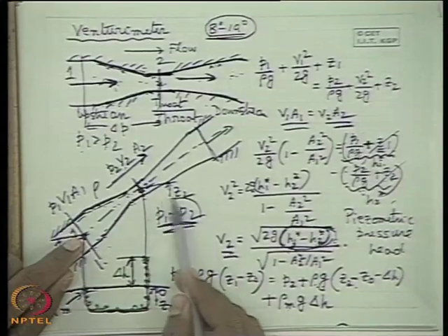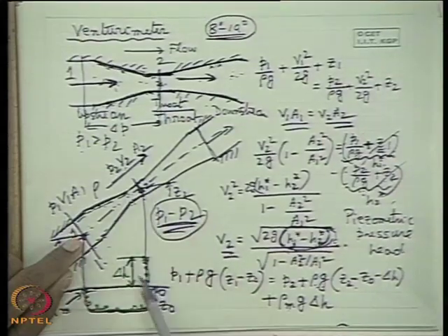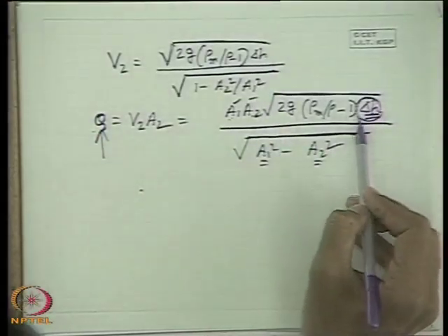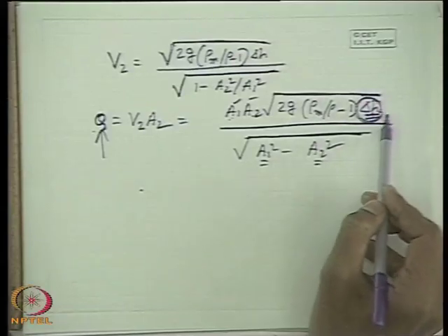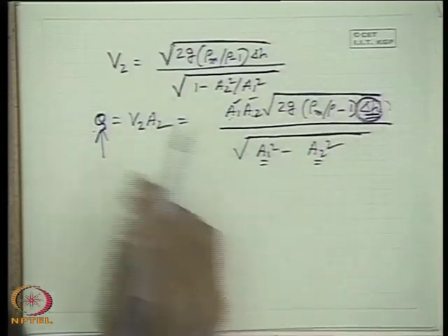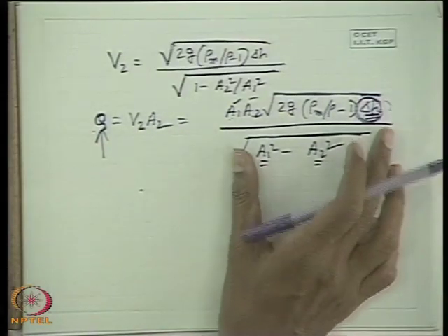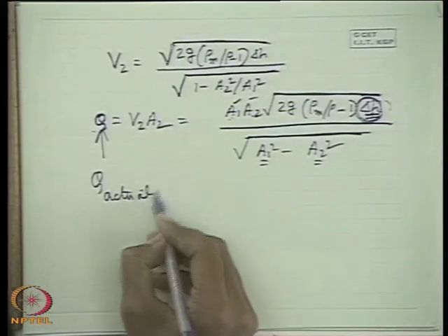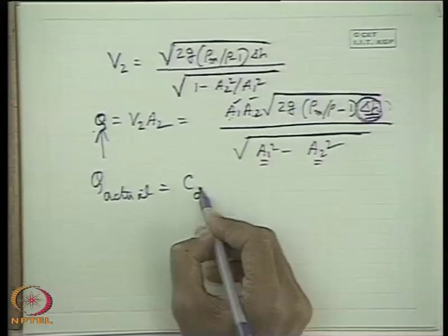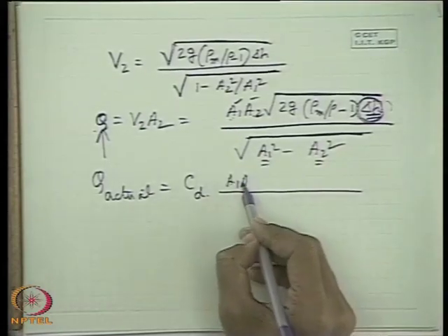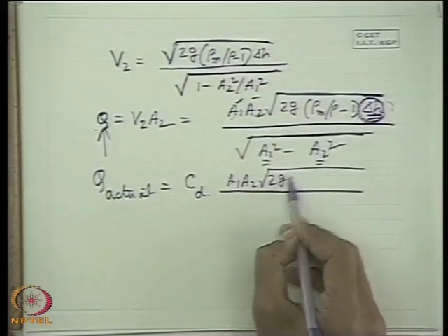So therefore actual pressure drop in a real fluid in this situation is more than that what is estimated by an inviscid fluid. So therefore delta H is more than actually what it could have been for the use of this formula. This formula is determined by considering the fluid to be inviscid. So therefore Q is giving a higher value. So for that we write that Q actual is adjusted by multiplying this with a coefficient, that is known as coefficient of discharge. So coefficient of discharge is now very clear.